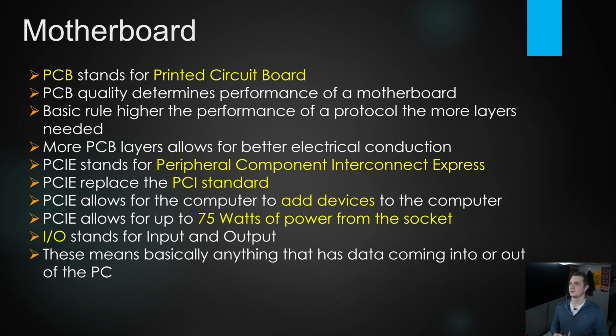So one of the things that we do need to talk about for PCIe is that power in general is 75 watts or less. So something like your graphics card needs supplementary power from the power supply to actually function. Your NVIDIA current gen GPUs can pull up around 300 watts, which is significantly higher than what the slot itself can provide. So it needs its own power source.